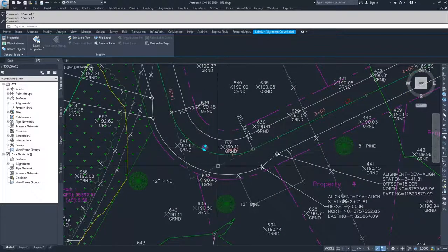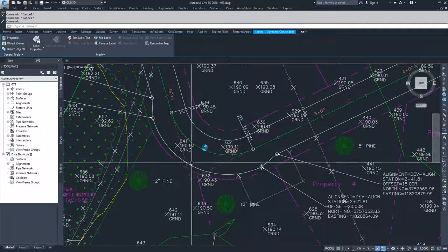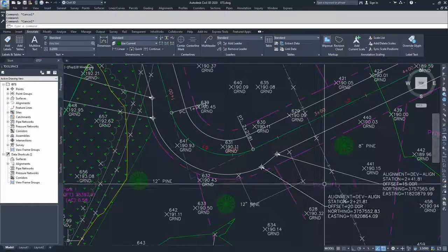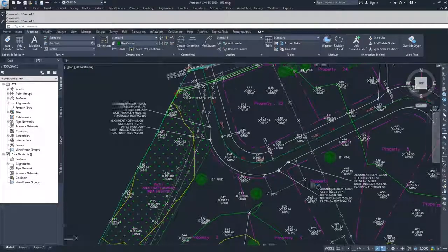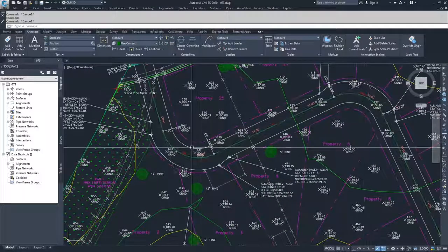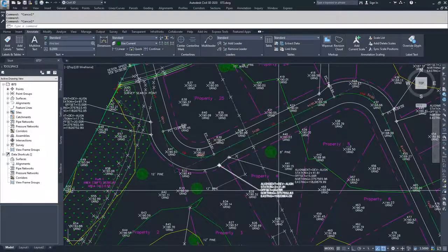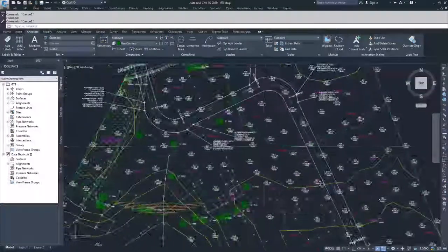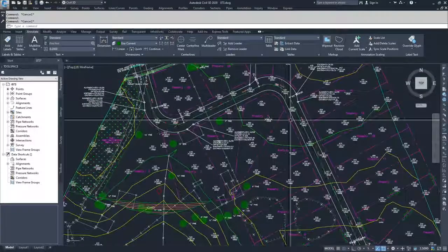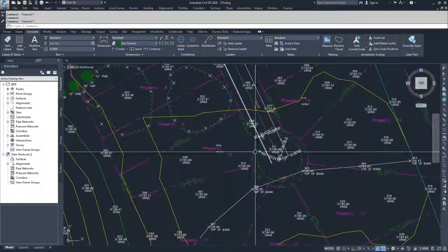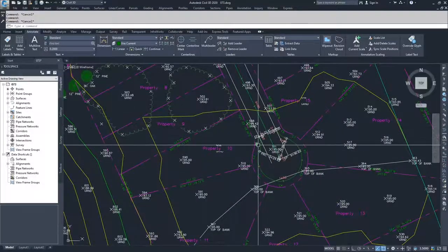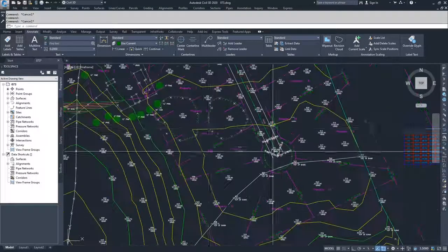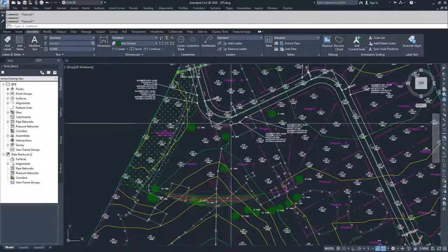When you select renumber tags, what you're going to run into is that this C9 is going to want to renumber to 1, and you're going to get an error message that says C1 already exists. Do you want to create a duplicate or move to the next available? The next available would actually be 11, so it would convert this C9 to C11. If you wanted to modify and have this as C1 and this as C2, you would actually have to renumber all of these to be C3 through C10, and then you could renumber these to C1 and C2.